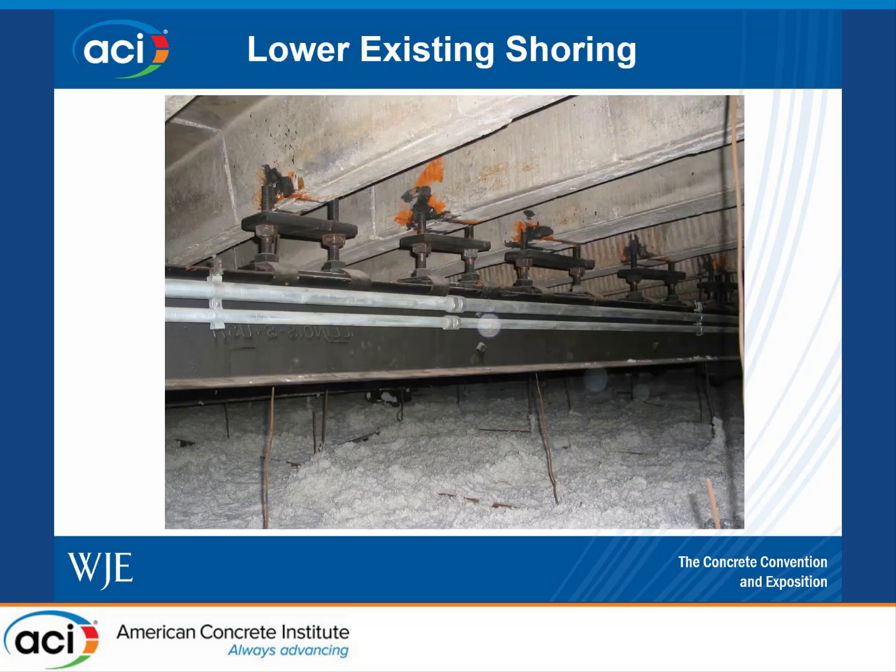One unique thing about this test is we lowered the existing steel shoring so the concrete structure could behave independently. The advantage to the steel shoring beams was that they could also be used as shoring if we had an unexpected failure. So we didn't have to install independent shoring. We just relied on the steel beam grid system after checking its capacity.